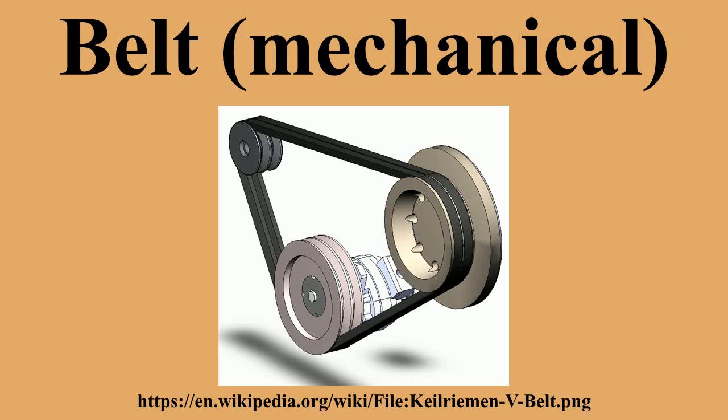Belt wear. Fatigue, more so than abrasion, is the culprit for most belt problems. This wear is caused by stress from rolling around the pulleys, high belt tension, excessive slippage, and adverse environmental conditions. Belt overloads caused by shock, vibration, or belt slapping all contribute to belt fatigue.